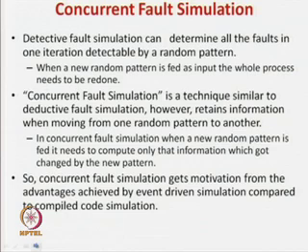In this case, what do we do? We find out the output or the input under fault or normal case, then we retain some values, or say all the values of the circuit. Then when we apply another pattern or another fault, we should be able to recompute only those portions of the circuit which got changed as an impact of a new pattern or a new fault. That is the idea, and this is missing in our deductive fault simulation. In one fault we apply, then we scan through the circuit by applying the rules in the table which you have seen, and find out the list of faults which are detectable. But we generally do not save anything in that algorithm, and again we have to redo everything.